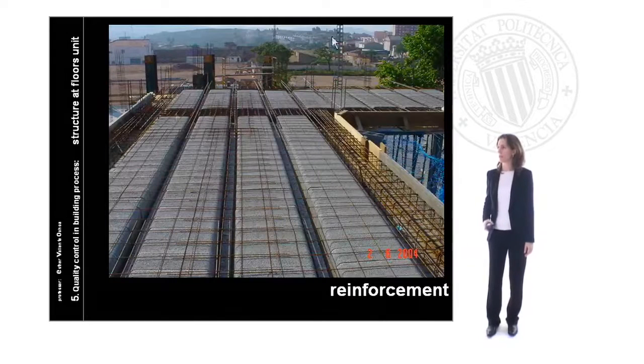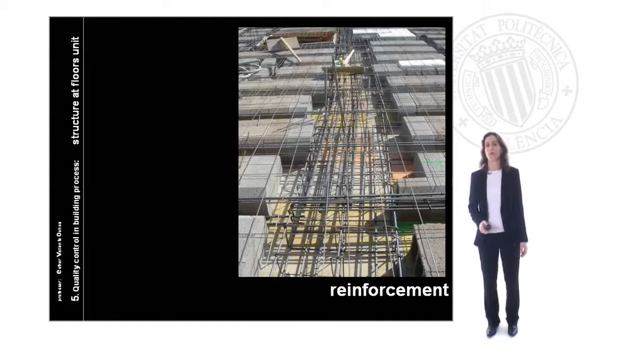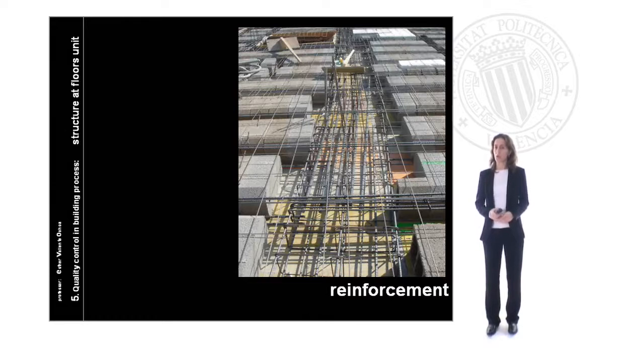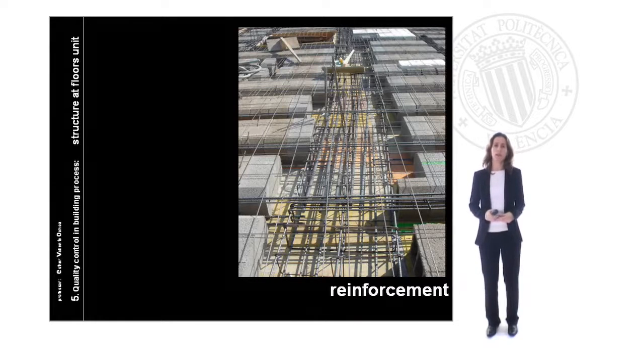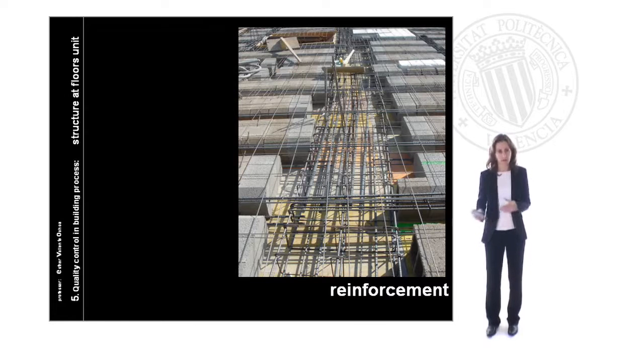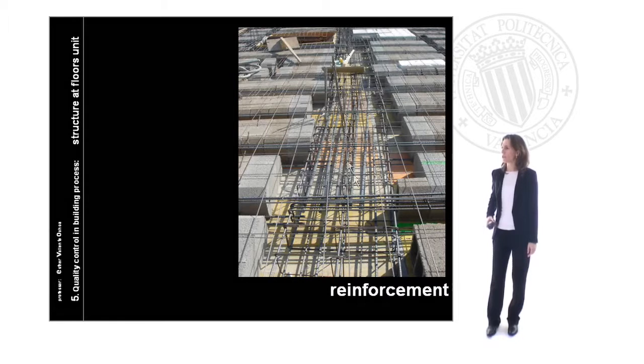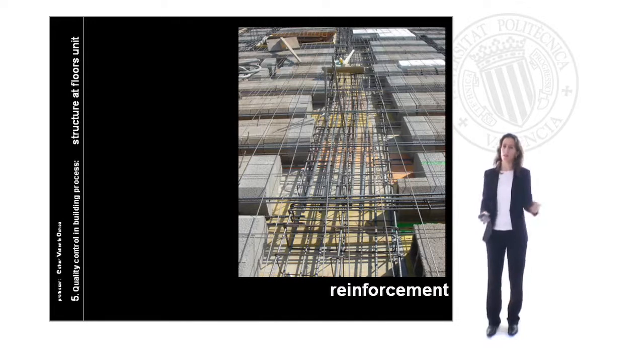Reinforcement has to be taken care of with a general view like this one: reinforcement at beams, perimeter beams, and the reinforcement in the floor, just negative reinforcement, and the square or steel net for the compressive area of the floor. Reinforcement has to be controlled very well before concreting. We will reject cases like the one in the picture at the side. The reinforcement has to be completely straight and completely following the detail of the project.